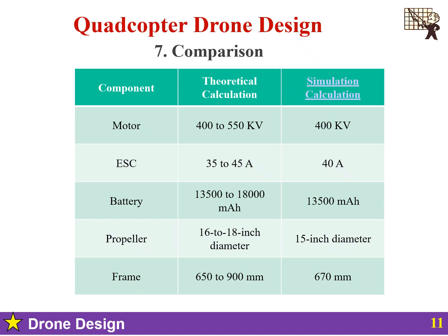Now comes the battery capacity. 13,500 to 18,000 mAh theoretically, but in simulation the simulation chooses the lower end, that is 13,500 mAh, prioritizing weight savings over maximum flight time. This suggests payload capacity was valued over endurance, a legitimate engineering trade-off.